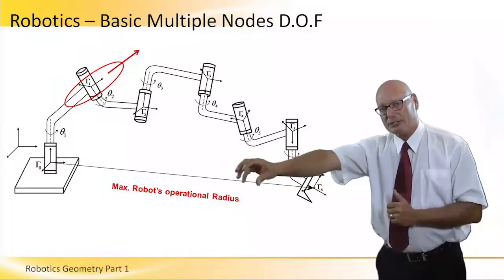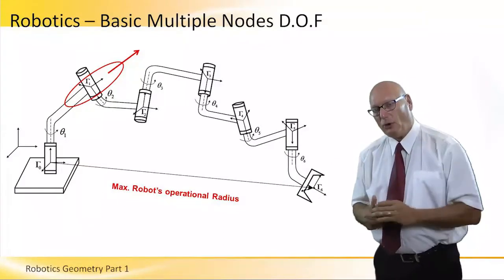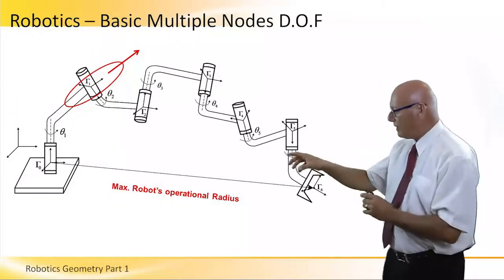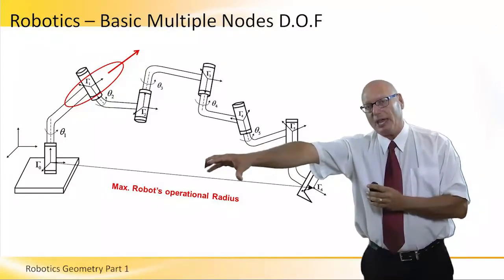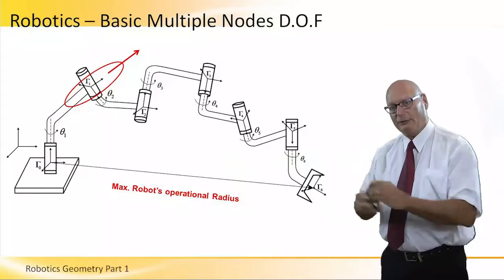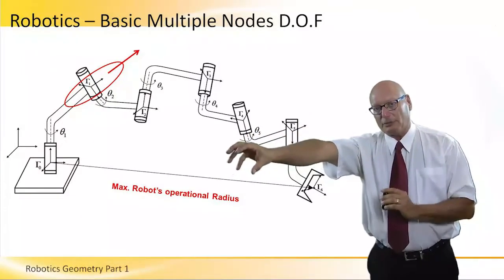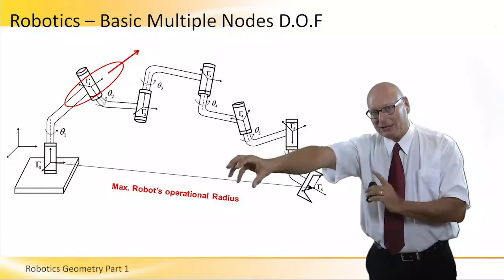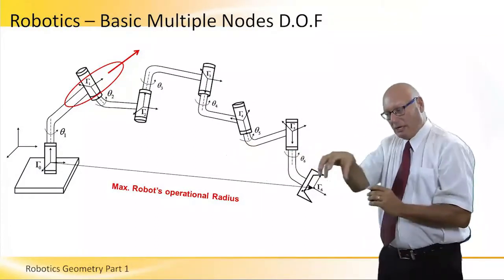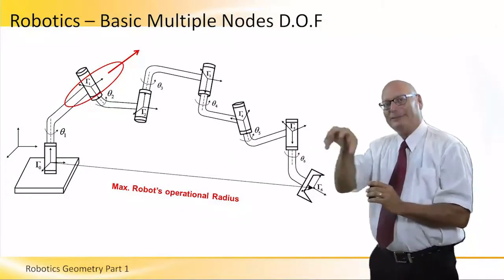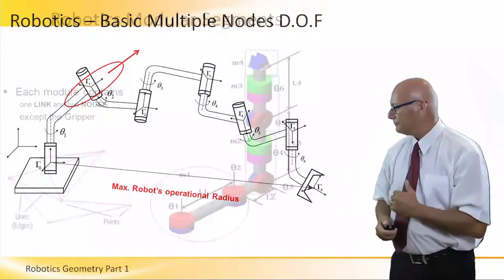Torques, vibrations, stability, reliability, repeatability, all these parameters we will cover. But when the robot is extended fully to the edge of the working envelope, it's problematic. It's problematic in the sense that it's hard to predict the quality of operation at the endpoint. So this is why we will try to work not at the far end of the working envelope. We will cover that much later.